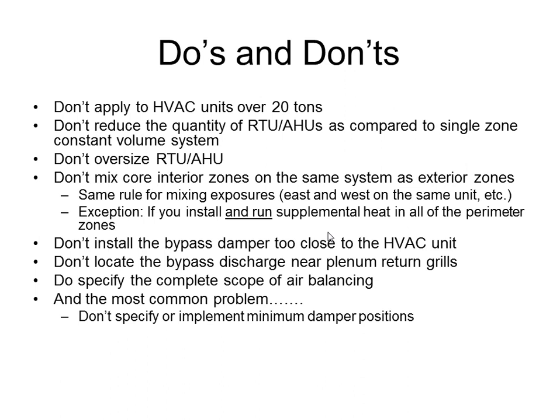And then the most common problem that we see, that we don't like to see, is specifying minimum damper positions for ventilation. Again, I'm not 100% sure of the code. There could be some ventilation code requirements, but when you have minimum positions set, you're going to be cooling spaces that require heat or heating spaces that require cool, and then your system's just going to be fighting itself. You want to try to get them to go fully closed in order to properly control a VVT system.